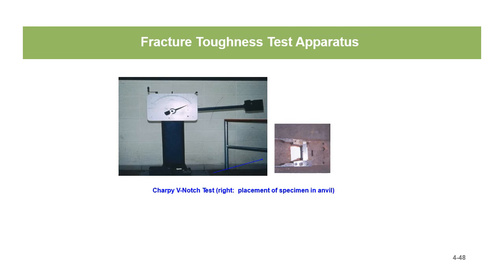And you also need to keep in mind that you don't just do one impact test specimen. You do three, or depending on what the customer or code requirements are, you do multiple tests, because you can have one test that is just absolutely screwy, absolutely out there from a numerical or a mathematical standpoint. So it gives you a better set of numbers if you do multiple impact tests, multiple specimens.